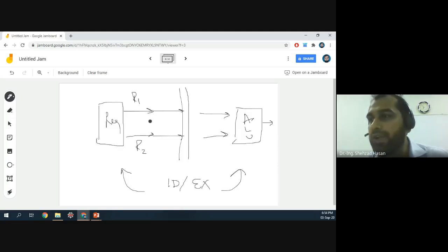Instead of doing these things through the ALU, what if we have a comparator over here, and we pass the values that we have read, that we are also going to store in that register, to that comparator, and the comparator is going to give us a signal whether the two are equal or not, right? Now if you do this, it means you are going to do that at the end of the cycle, right?